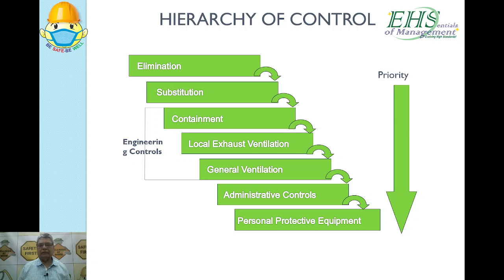See, try to understand, when you do the grinding operation, the sparks and burrs come out, and you just can't stop that, because if you completely cover the grinding wheel, how will you grind? So burrs are going to come out, and you have to have eye protection and wear goggles. The goggles create a barrier between the process and your eyes, right? In such cases, personal protective equipment is used, and mind well, personal protective equipment is the last resort.